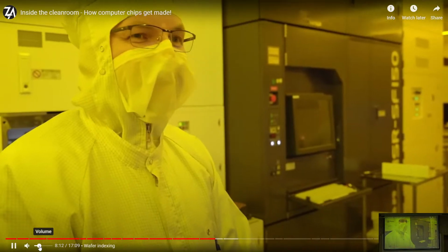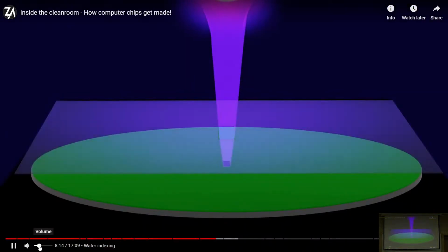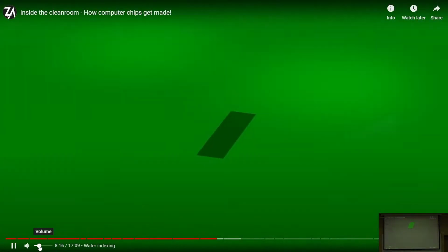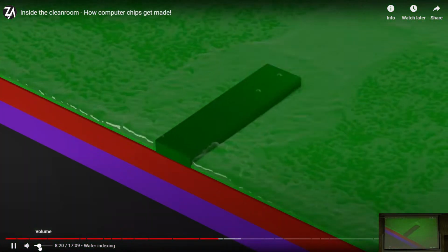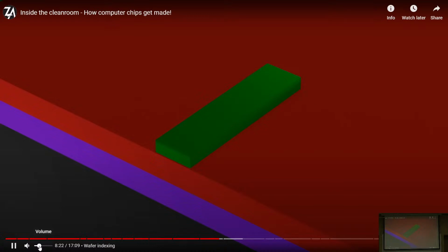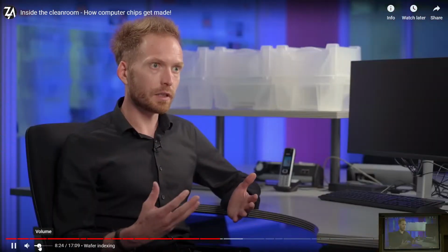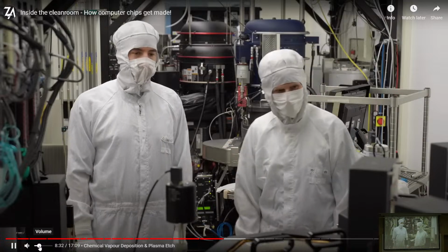Yeah. Okay. After the photoresist is exposed to light, it changes its structure, and then we can develop it so we can remove the exposed regions. Once we have the patterns, the photoresist acts as a mask, and we can do the etching then. So to etch our deep trenches, for example, this is a reactive ion etching tool.